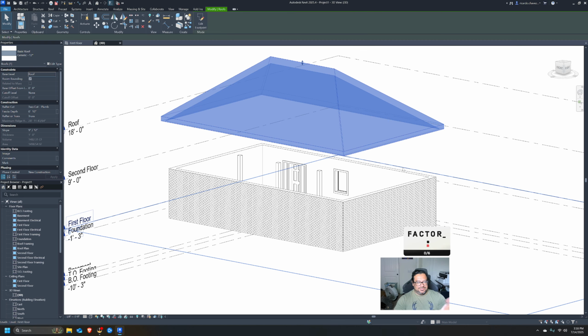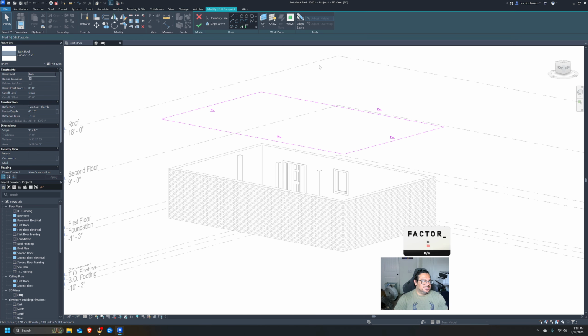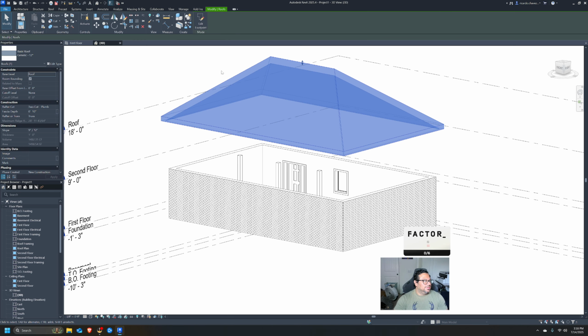We're higher because our walls are at 9 feet, right? And you can always adjust this. So if you want to make sure that everything is, say, 4/12, you can change it here. Or if you see here on this left side where our properties tab is, where it says slope, since it's all one unified slope, we can change it all here to just say 2 by 12. Or we can do 2 inches.